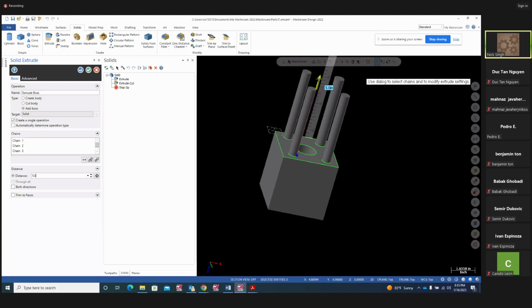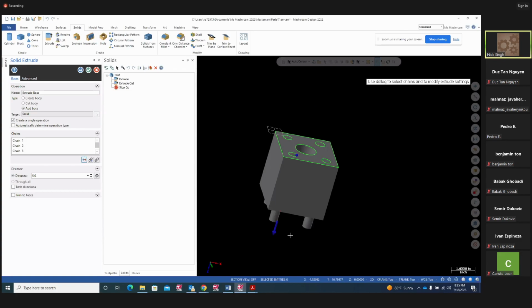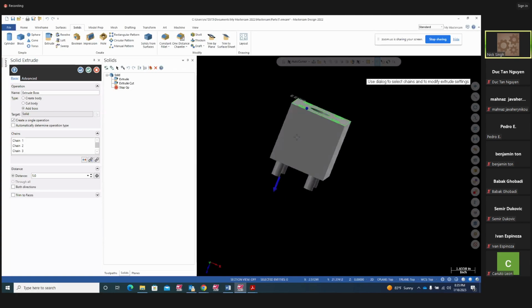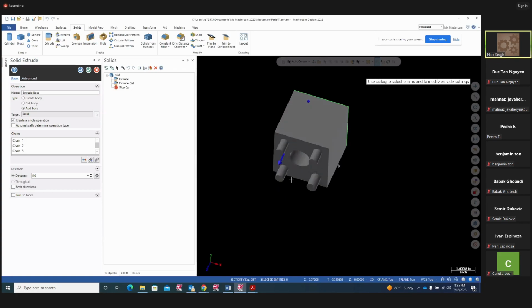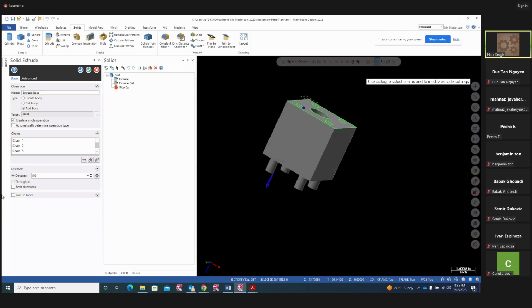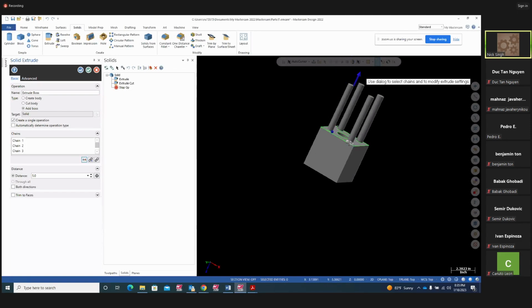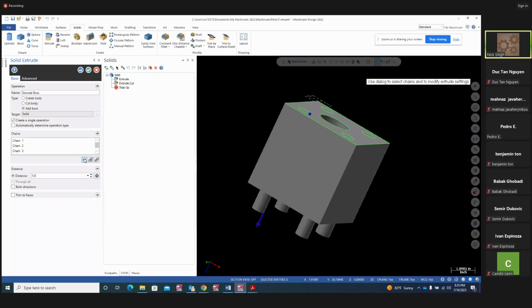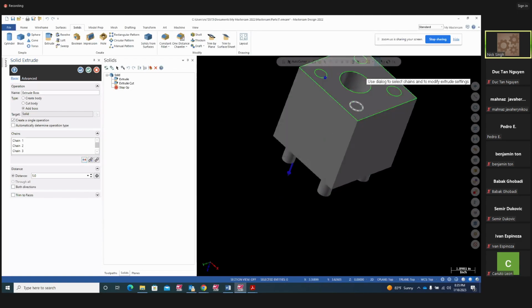That's the direction here. You can change. Just click on that. Just hit this, either say reverse in that direction. It's still adding a boss, but it's going to go 5 from here. So you will not see 4 inches. You're going to only see this 1 inch extra in this case. If you reverse direction, it will go 5 inches from the geometry. It measures your distance from the base, from the geometry. Even if you go another direction, it's going to be 5 inches from here, guys.